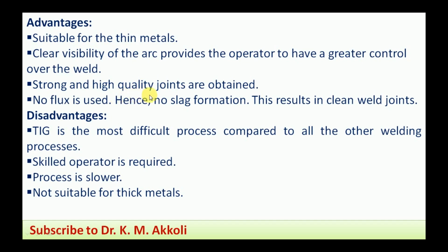Then strong and high quality joints are obtained from this welding. No flux is used. A flux coating is not used on the electrode. Hence there is no slag formation. This results in a clean weld joint. Those are the advantages associated with TIG welding.